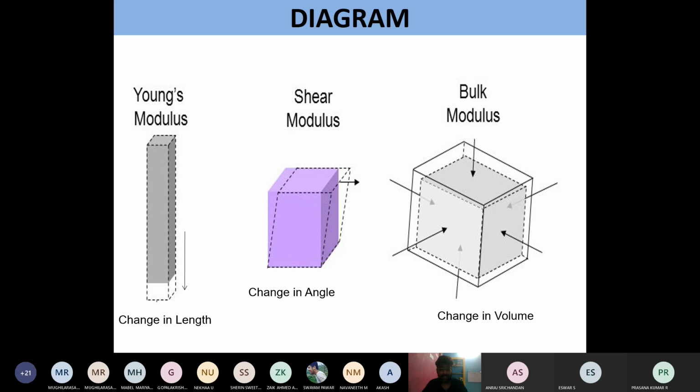See here, the dotted line shows the angular change. So how much the medium is deformed, how much the medium is tilted, how much the medium is rotated. That rotation, that change, shear, that tilt, is measured by this position. The dotted line is the changed position. The straight line is the original position. In between, in a smaller region, that region is nothing but the shear. It's nothing but an angle. That angle is theta. So this is the second one.